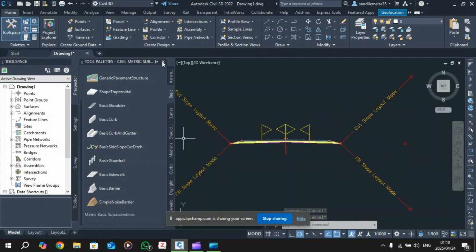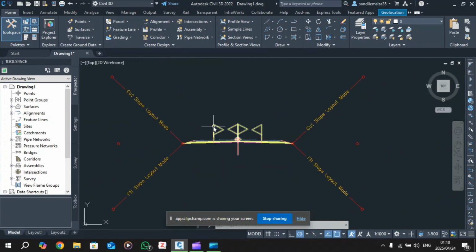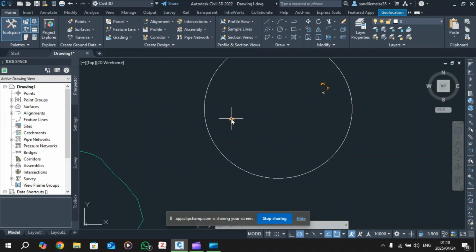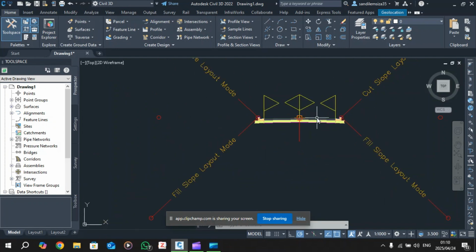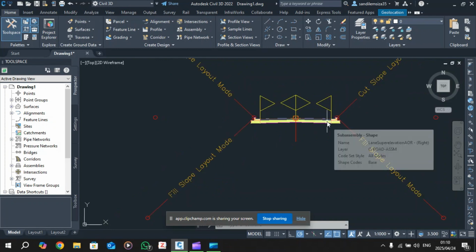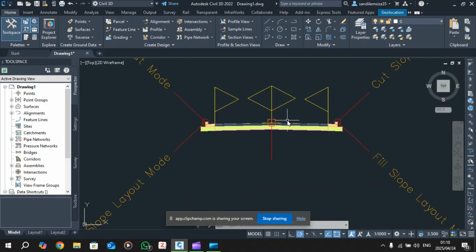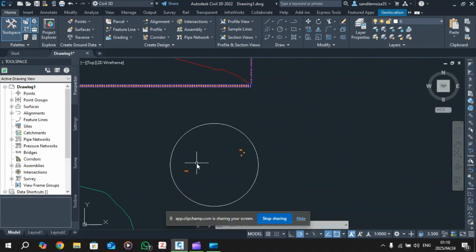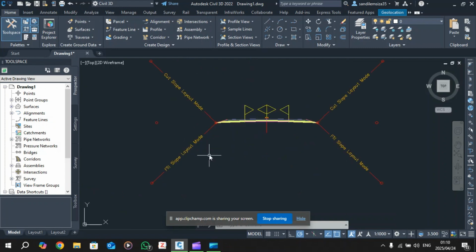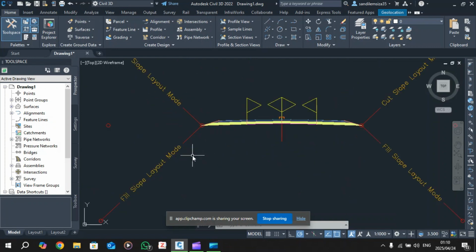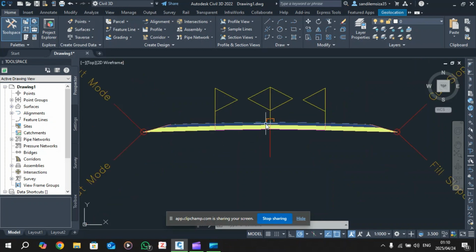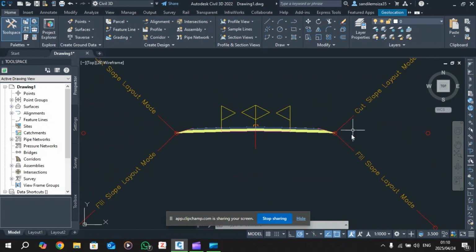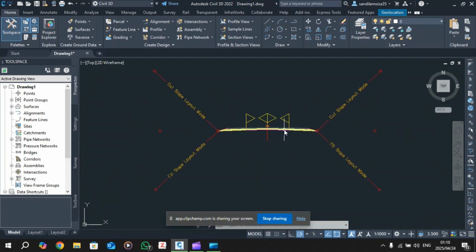Okay. So I am gonna exit tool palette for this because remember we are trying to replicate this right here. So as you can see, this is the full section as a template from Civil 3D, and this is ours. So what we need now are what we call our half sections. So your half sections are like your left side is the same assembly but only the left side showing, and then one with the right side, and then we need a curb return.